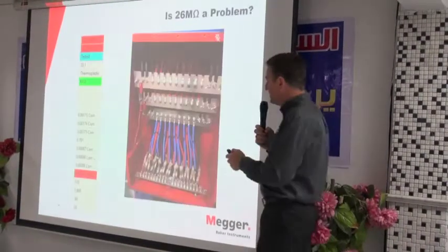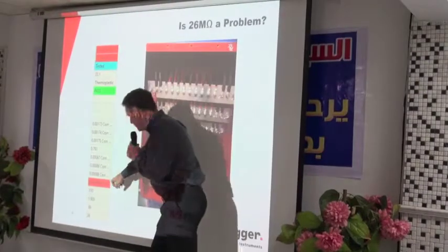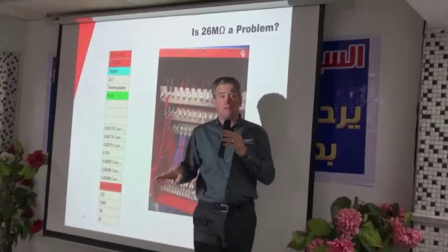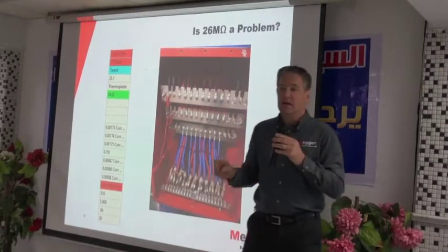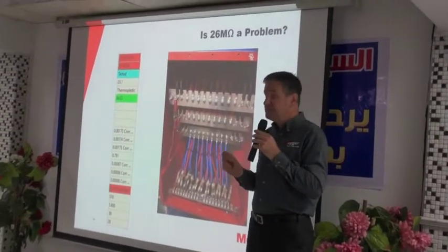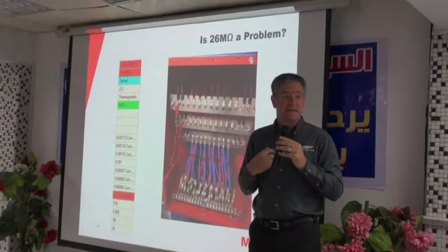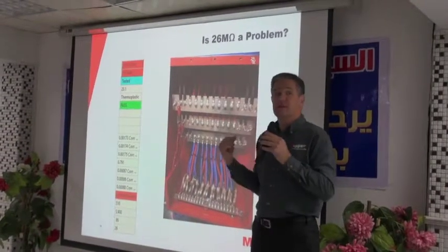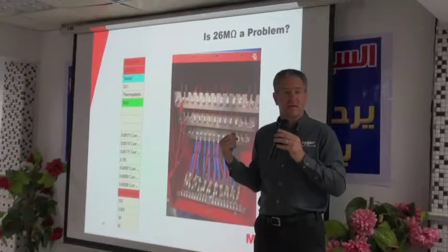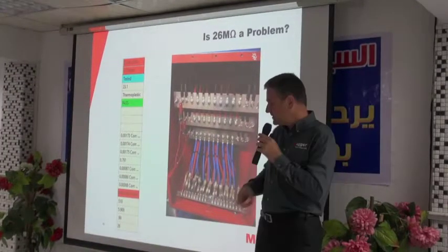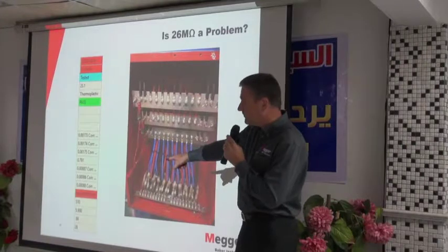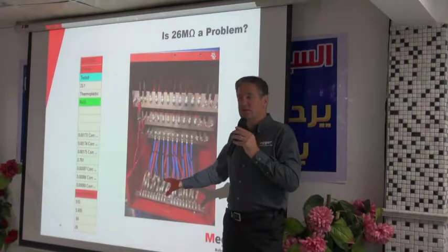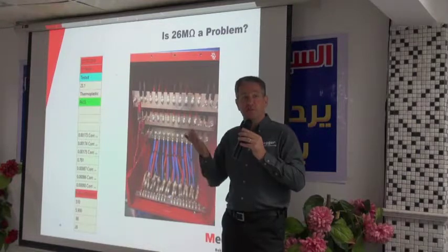Okay, my tester, for this failure, this is automatic failure. The tester will stop and tell you you have a problem with minimum megohm. In my program, I use 50 megohms at 40 degrees. That's my standard. So my standard is 10 times the international standard. That's why the value is red. So this is a very simple case study, but it shows you that you need higher values for reliability.